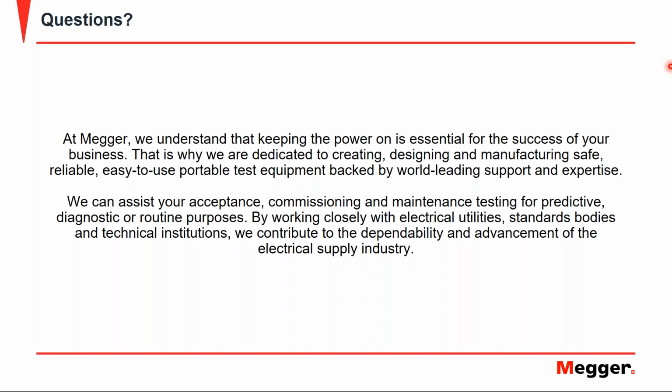Thank you, Hein. Over to Jason. When doing offline testing, we would remove the cable with termination from the switchgear bus. Does this loose end contribute to corona problems, especially if the cable termination has the loose strands protruding from the termination? Okay, so this is a good question about the setup whenever we're taking partial discharge measurements.